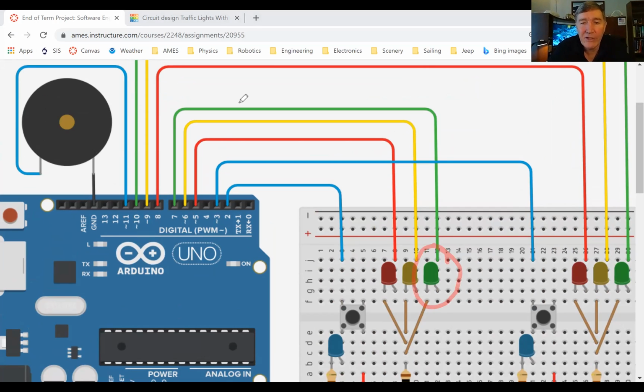So that's a green light bulb. And I want to tell the Arduino to turn it on, right? So what I can do then is if I follow along this wire here, this is the electrical wire that is connected to the green light bulb. And if I come down here, I can see that it is connected to pin number 7. So each of these pins here has a number. So the green light bulb is plugged into pin number 7.